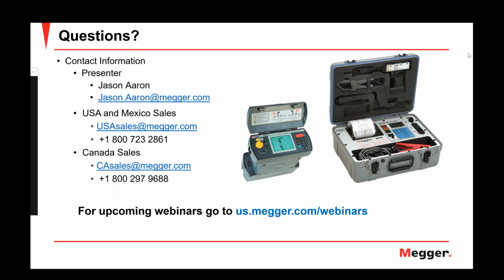One typical example is NiCad batteries. With NiCad batteries, you can do the measurement and you get a result. Under certain conditions, the impedance on a NiCad battery might change, and it is a clear indication that the battery is in a failure mode, and the capacity is probably already gone, or you have very reduced capacity. However, it's not that it will always change when the battery deteriorates.